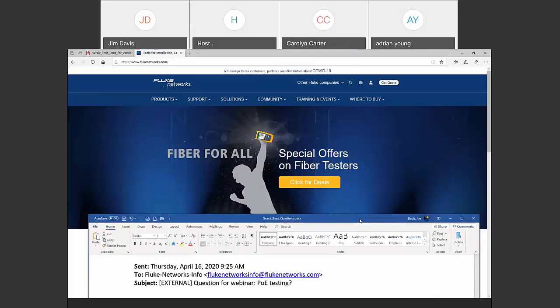And I've heard that can be a problem, especially if you say use jacks that are designed for solid pair cabling and are punching down twisted pair cabling into them or the other way around. In other words, if you're mixing the connector type with the cable type, that can lead to resistance problems. This really shows up with RJ45 plugs. If you are terminating RJ45 plugs onto horizontal cable because you're going into an access point and the customer doesn't want a jack in the ceiling there, it's very important to get the RJ45 plug that's designed to terminate solid cable.